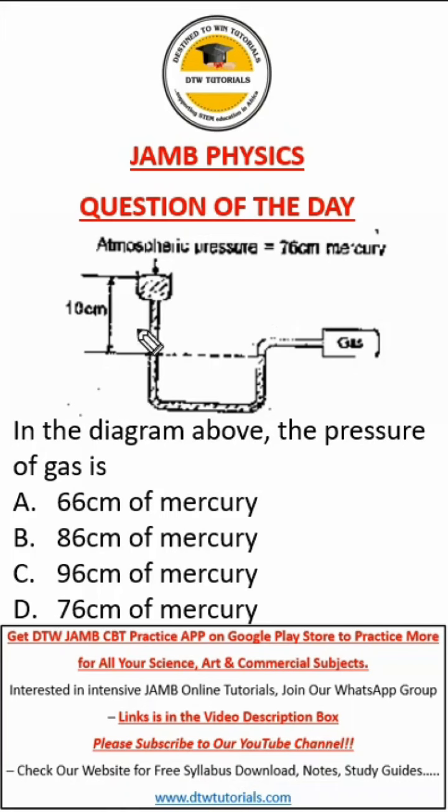So how do you measure? This is the gas being passed through this tube. So how do you now get the pressure of this gas? Because that's what you're trying to measure. It's just simply the atmospheric pressure plus the height difference. So it's just 76 plus what? 10. And our answer here is option B. As simple as that. Simple. So you have to get it.